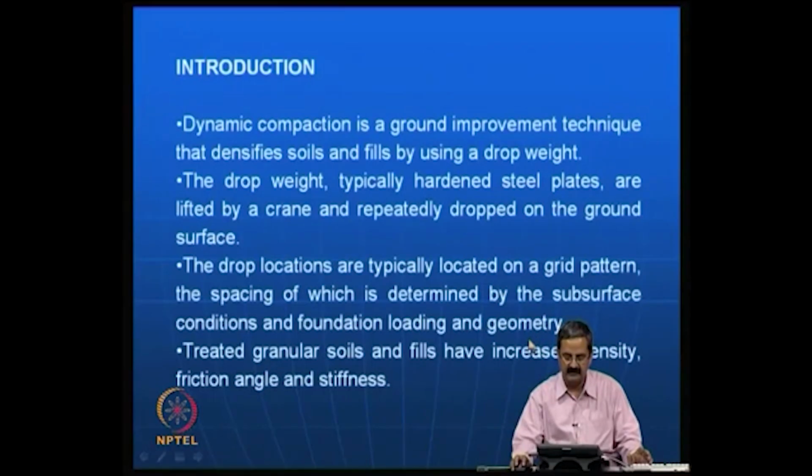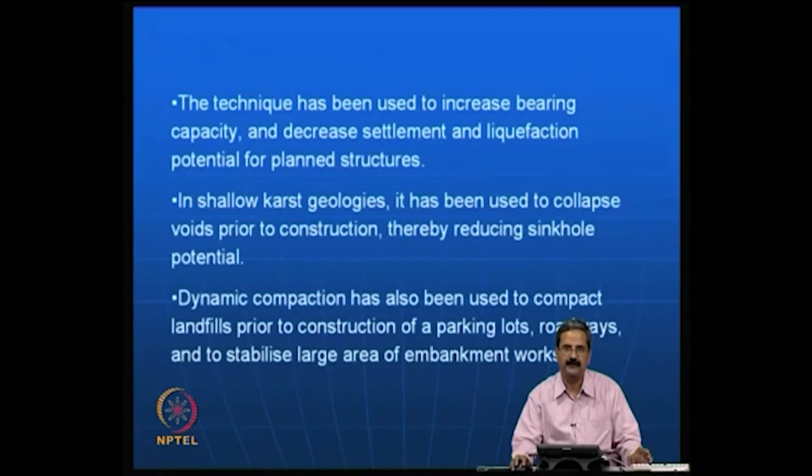Essentially, most of the time we have a grid pattern, and the main thing is the subsoil conditions, like to what extent the soil needs to be improved, and then what foundation loading is coming, and the geometry. All that is very important. Treating granular soils and fills has always resulted in increased density, friction angles and stiffness. We will see how this can happen.